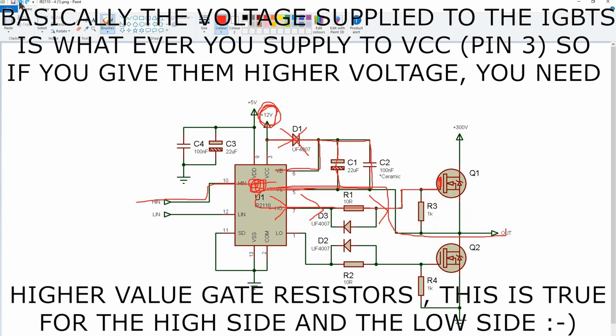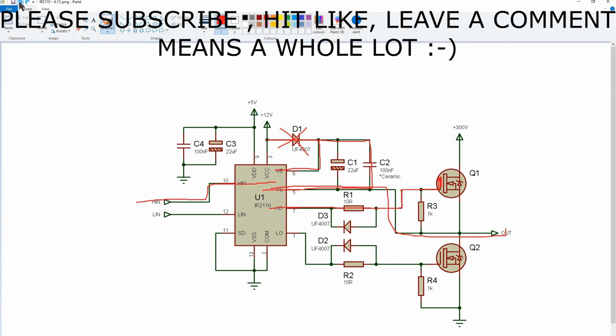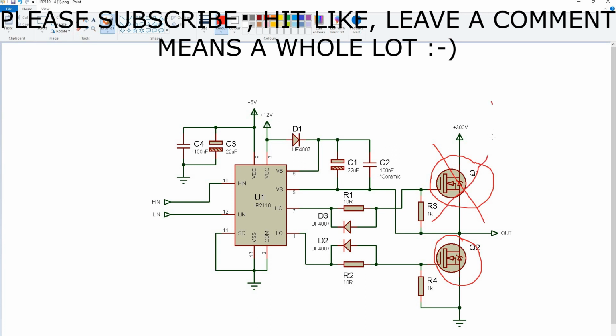Otherwise you just cannot fire a high side FET without using P-type doping. So these are both N-type. The reason we don't use P-types is because it's just hard to get hold of, expensive, and all sorts of nasties. So hopefully that's the driver circuit sorted out for you.